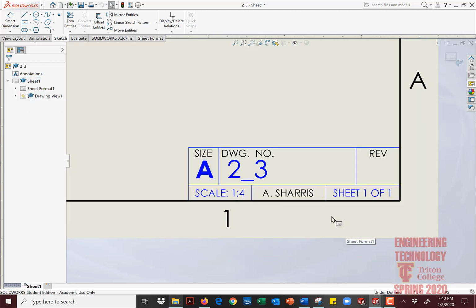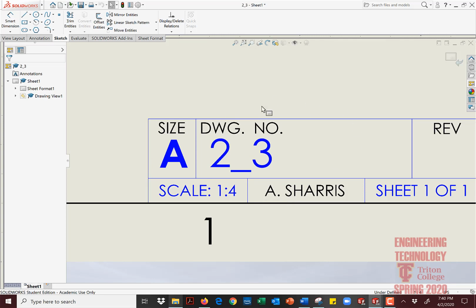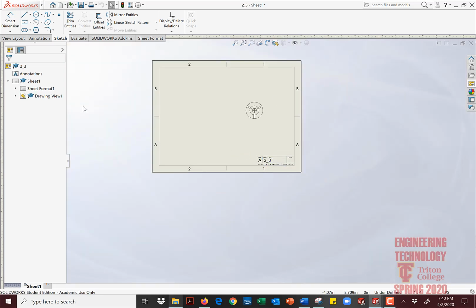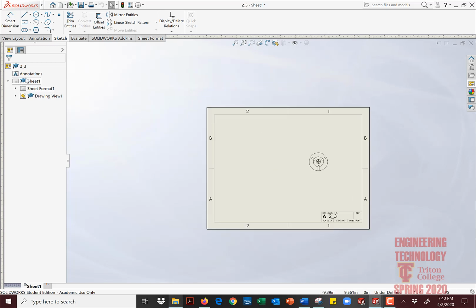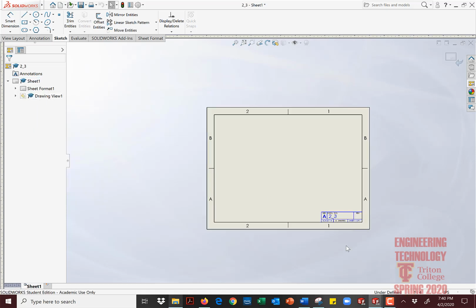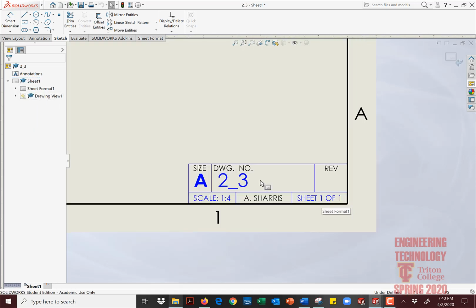Okay, now when you do that, I actually went in to edit the content in here. That's not what you want to do, so you X out of that. So what you do is click on this right mouse button, properties. See how that happened? You pick edit sheet format. Why? Because it's right there. It looks convenient. But when you do that, you find out you're editing the sheet. I guarantee this will happen to you. Don't worry about it. Just appreciate, okay, wait a minute.